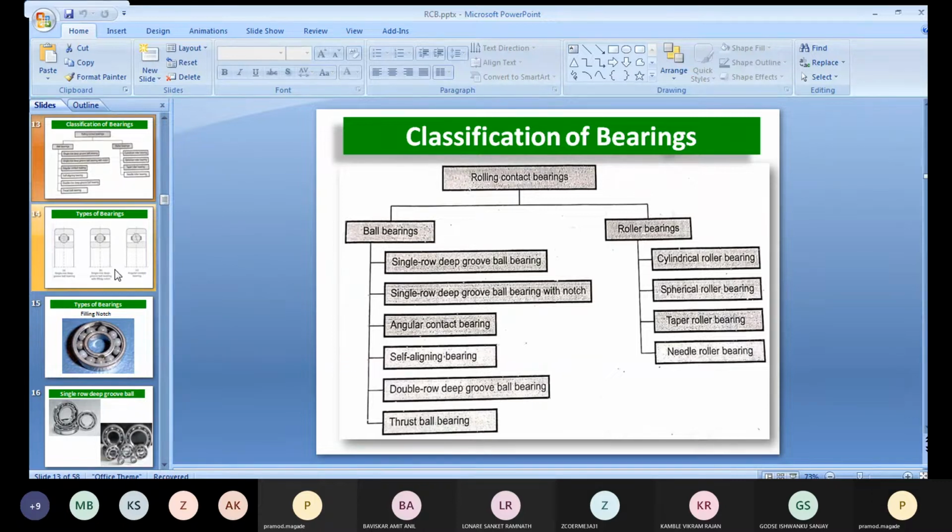And in the case of the roller bearing, roller indicates it is just a cylindrical structure which, at the time of working, will maintain an area of contact or line of contact, correct? But in the case of the ball bearing, it will maintain a point of contact. Because of its point of contact, deformation occurs at the edges, so we cannot say the deformation in a ball bearing is always equally distributed to all sides of the balls. No. So this is the major difference.